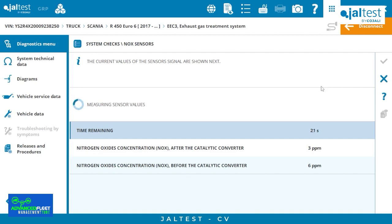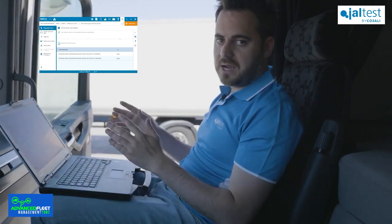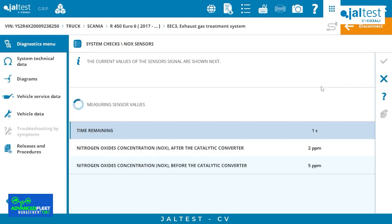Little by little, you will see that the values are starting to be stable, and then we will be able to advance to the next step and make sure that the zero value is within the correct values allowed by the ECM. Alright, so the NOx sensors are heated up. As you can see, there is a counter of 40 seconds left, during which we will be reading the ppm values for the NOx sensors before and after the SCR.